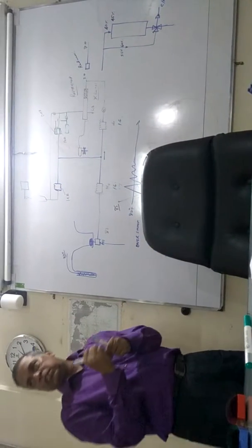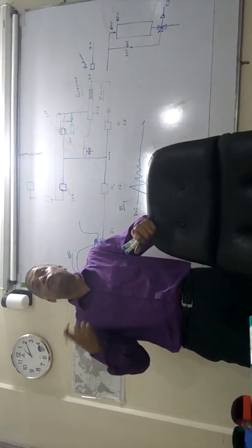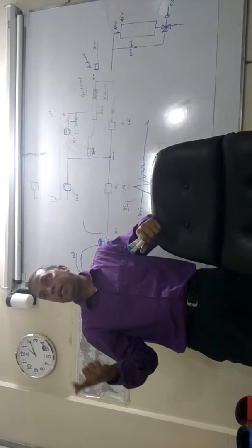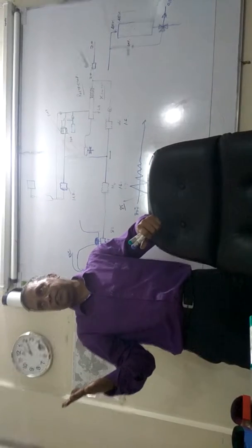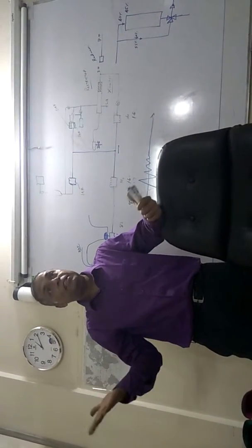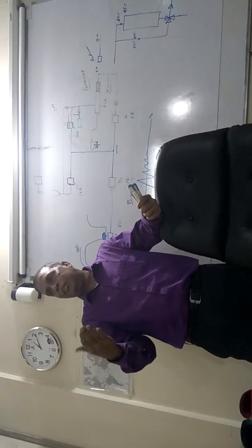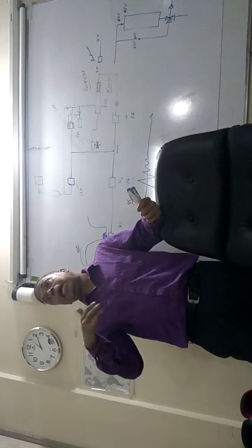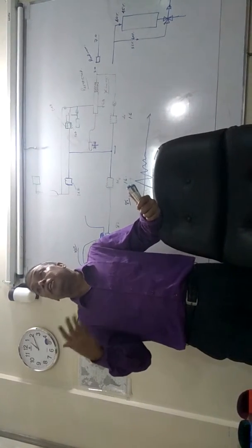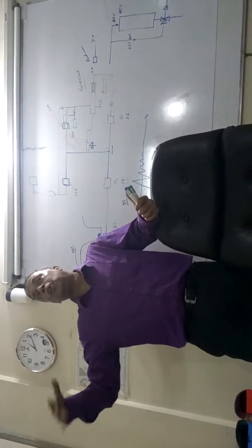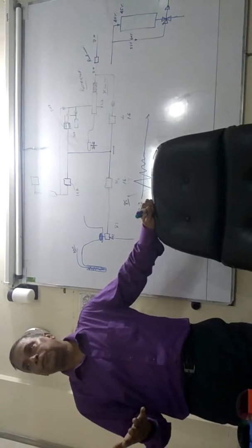So overshoot is what? The controller is too sensitive, too fast. Okay? Corrective action is too high. Right? In such a situation, when deviation is corrected and the parameter is creating another deviation in the opposite direction, this is called overshoot.